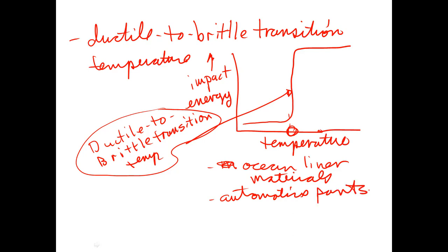Those that might be subjected to both high temperature and low temperature and see some impact, like tire rims, for example. Fortunately, this phenomenon is unique to low carbon steels, and we can tie it back to it being a rate phenomenon that's unique to body-centered cubic metals.